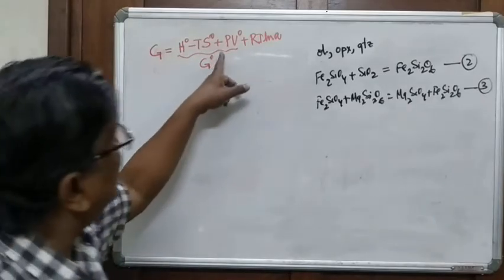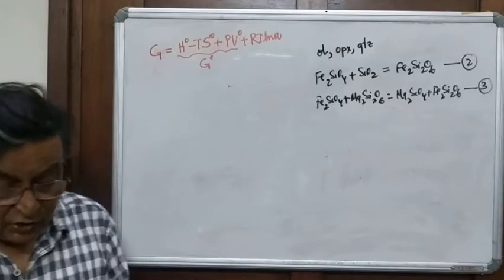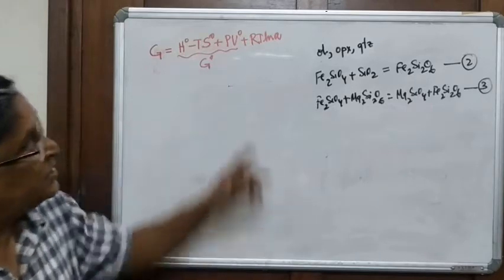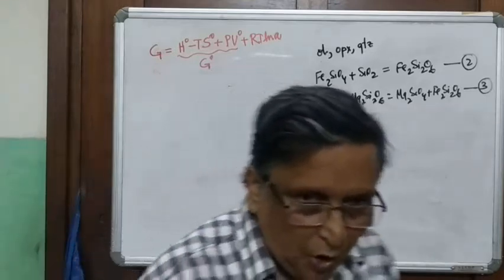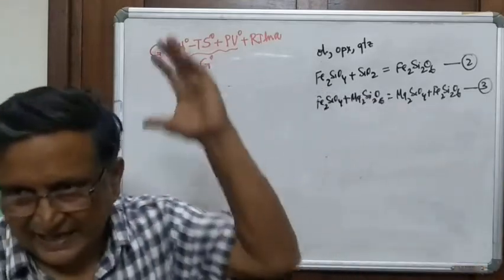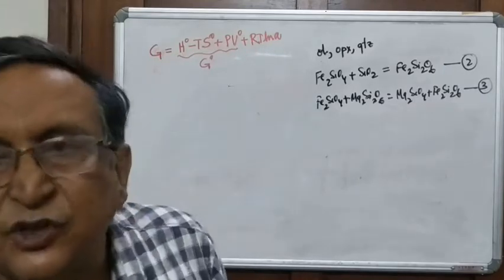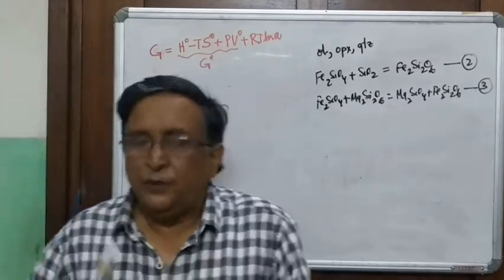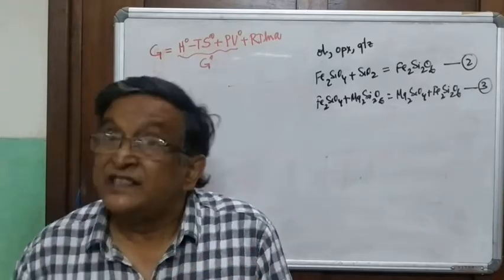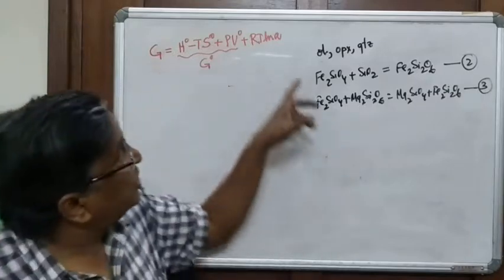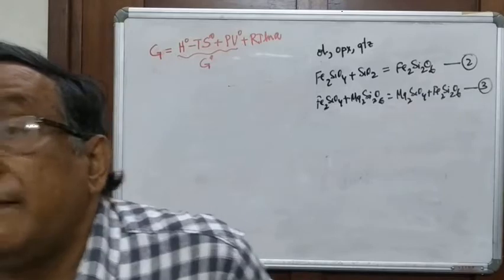Remember, in doing so, we have made certain approximations. What are the approximations we did? I will recollect it from that class. All the heat capacity terms were neglected. And the thermal expansion and the isothermal compressibility data, which account for the change in volume as a function of pressure and temperature, were neglected because we took volume as independent of pressure and temperature effect.